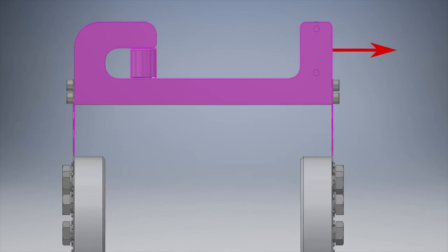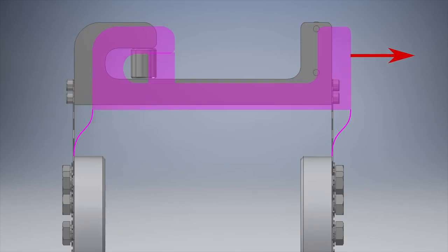The way the spring is currently designed, I'm not sure how much the spring can move until it will touch the spiral guide. The reason is just the way the spring moves when pulled by the wires, like this. This detail needs improvement. All I know is that I want to proceed in the spirit of the compliant mechanisms.